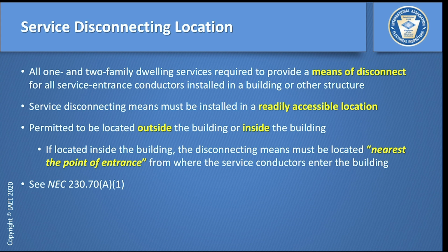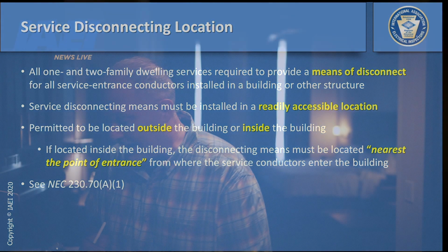All right, now we're getting into the service disconnect location. Now, one of the reasons why somebody would not want to call a conductor a service conductor is that the moment you call a conductor a service conductor, that disconnect is a service disconnect. Once you call that a service disconnect, you have to follow all the rules for the service disconnecting means.